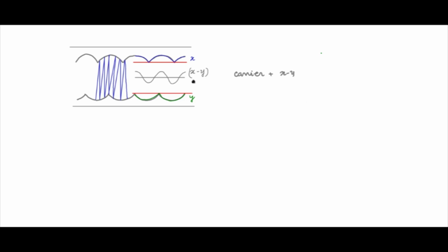So normally half of that value is added to emulate the space vector PWM, and this would be the triplen injection, and then you will get exactly a similar type of modulation to what we discussed in the discrete case.